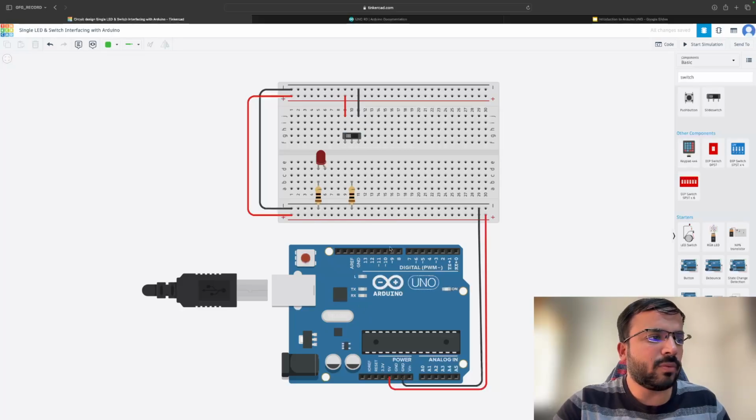And simply now we connect the breadboard, take the ground, take the 5 volts, connect the plus row and the minus row accordingly, right, from 5 volts and ground, so that the breadboard is connected, right? Similarly on this row, right? Now I think the LED connection is always clear to you, right? So now what we do, let's connect. So similarly here also, let's output the LED from pin 13. Let's configure pin 13 as an output and drive the values.